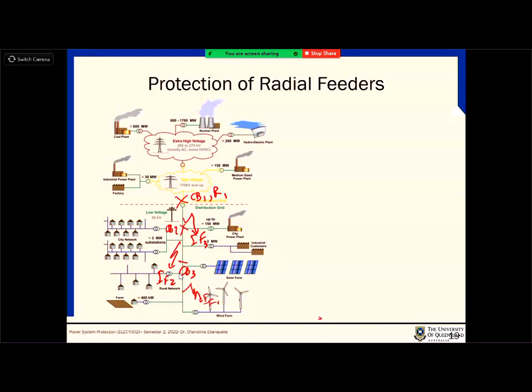For some small issue, a tree branch suddenly touching, or wind, or an animal going through, or a snake short-circuiting the 2 lines, you don't have to go back and fix it. Those are sort of self-healing things. So that was one of the advantages. And the other advantage is that, as I said, the number of customers who lose power is very minimal.